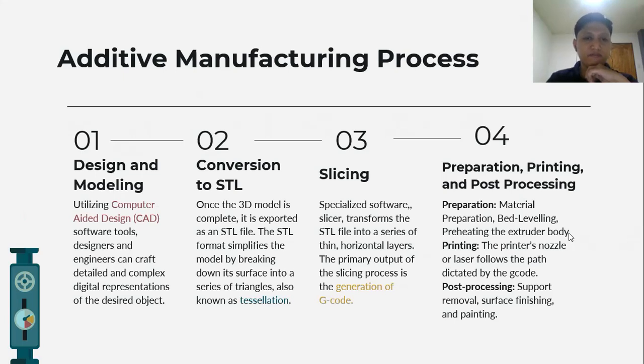This format simplifies the model by breaking down its surface into a series of triangles, also known as tessellation. This is done through CAD, where you can export your file into an .stl file for later slicing.